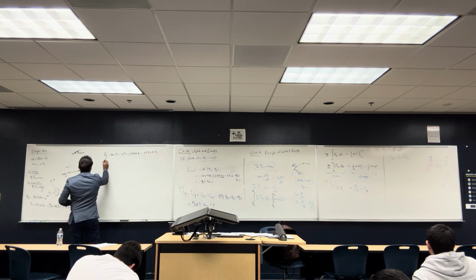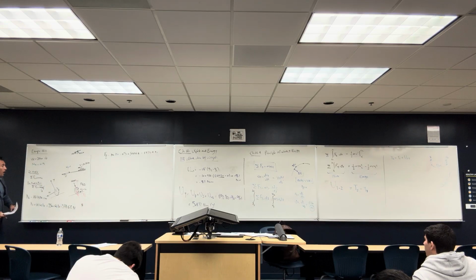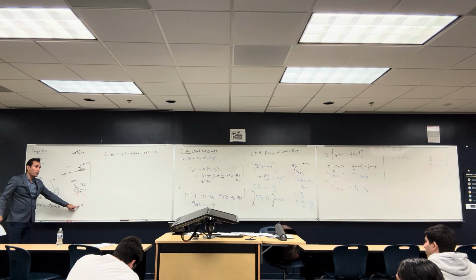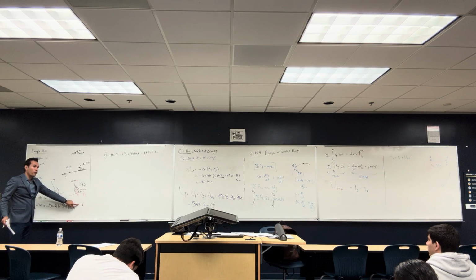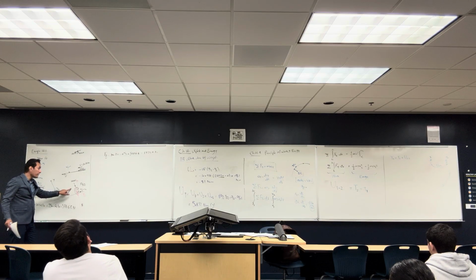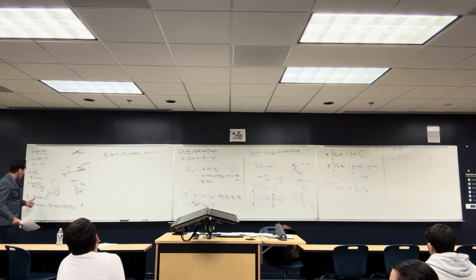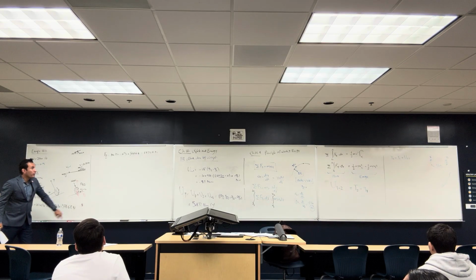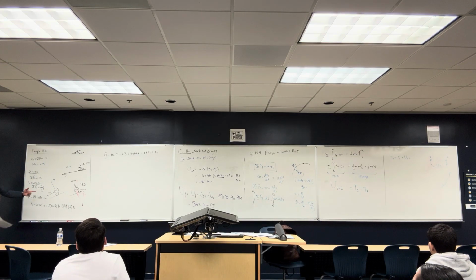I got the friction force. Why am I doing all this? I already know the weight, it's given, but I don't know the value of the friction. To find the value of the friction, I need the value of the normal force, and to find that, I have to use Newtonian kinetics in the direction of the normal force, which is the y direction.